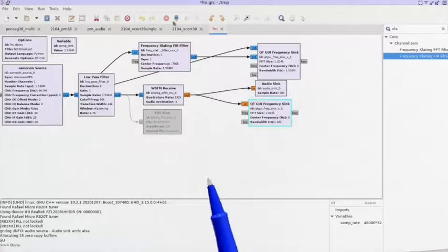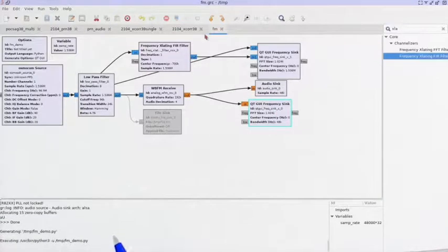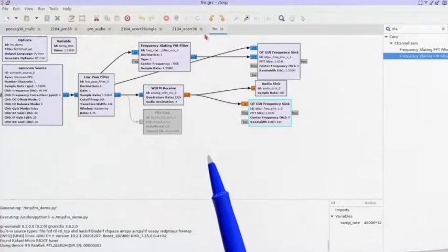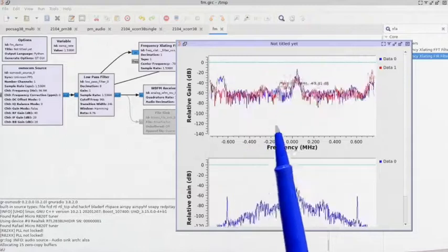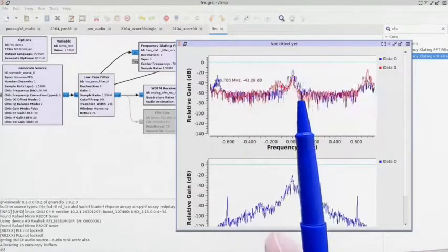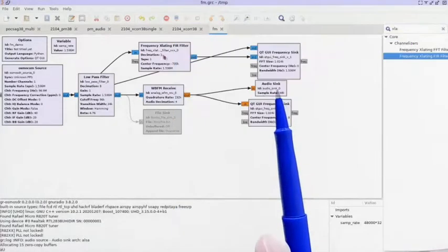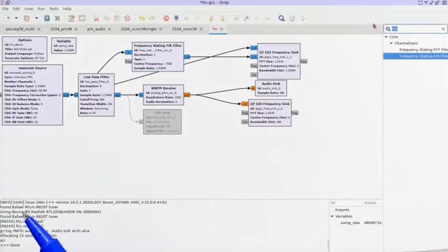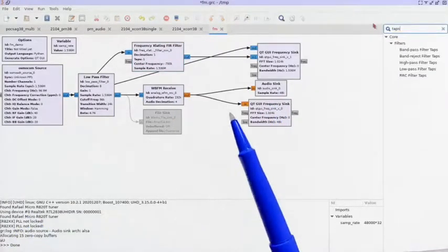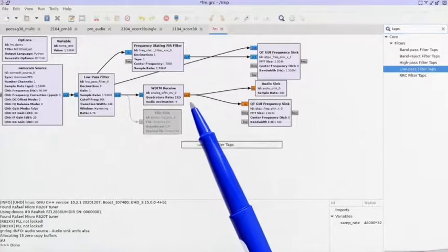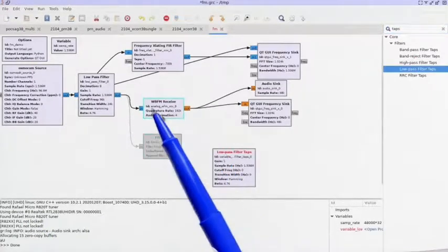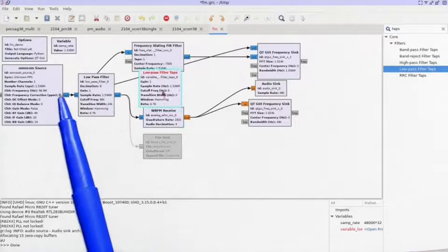So when running this spectrum analysis, we see on the center 0 hertz here that the old initial station is centered, and the station that was here on the side has been brought to 0 hertz. So both stations are now ready to be demodulated. We already have a first demodulator on the frequency that is centered on 96.9.